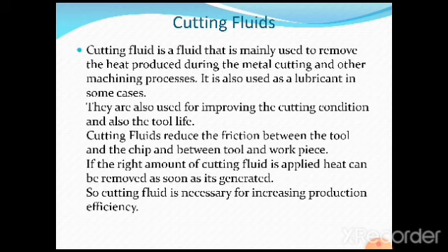friction, the amount of power lost due to the generation of heat varies from 20 to 30%, and hence to reduce it the use of cutting fluids is very much necessary. It is possible to reduce nearly 20 to 30% of the heat generated by the application of cutting fluids. The cutting forces can also be reduced by using suitable cutting lubricants. By using certain lubricants it is possible to reduce the amount of cutting force, and thereby reduce the amount of heat generated at the tool chip and the work interface.